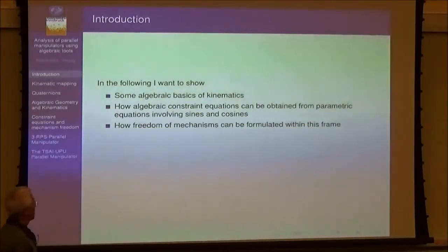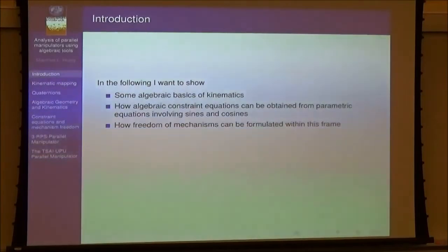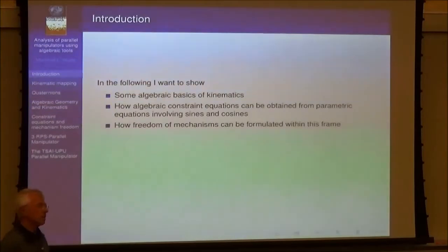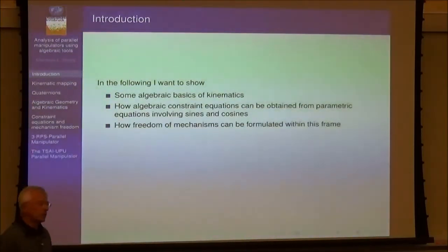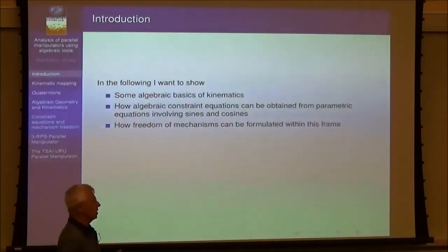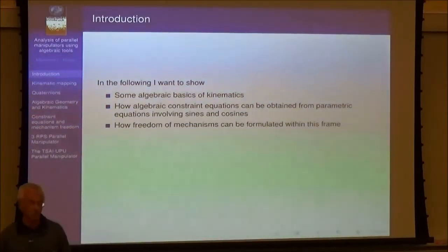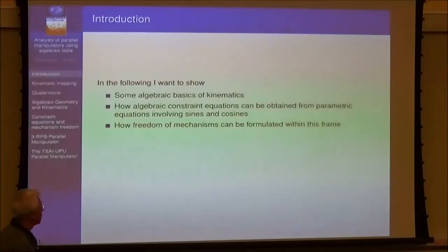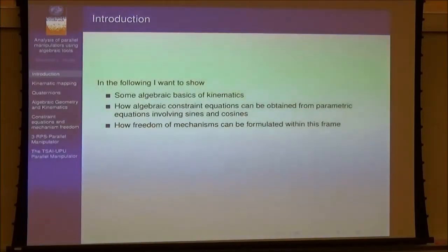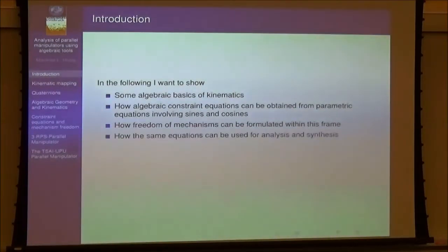So, I am claiming when you have the right description with kinematic constraint equations, then you can find out that such a system has an unexpected degree of freedom which you cannot compute with your Grübler-Kutzbach formula. I will show you some examples in this talk.